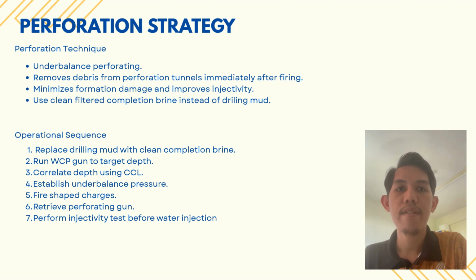For the perforation technique, we selected underbalanced perforating. During perforation, the wellbore pressure is maintained slightly lower than the formation pressure. This allows formation fluid to flow immediately after the charges are fired, cleaning debris from the perforation tunnel. As a result, formation damage is minimized and injectivity is improved.